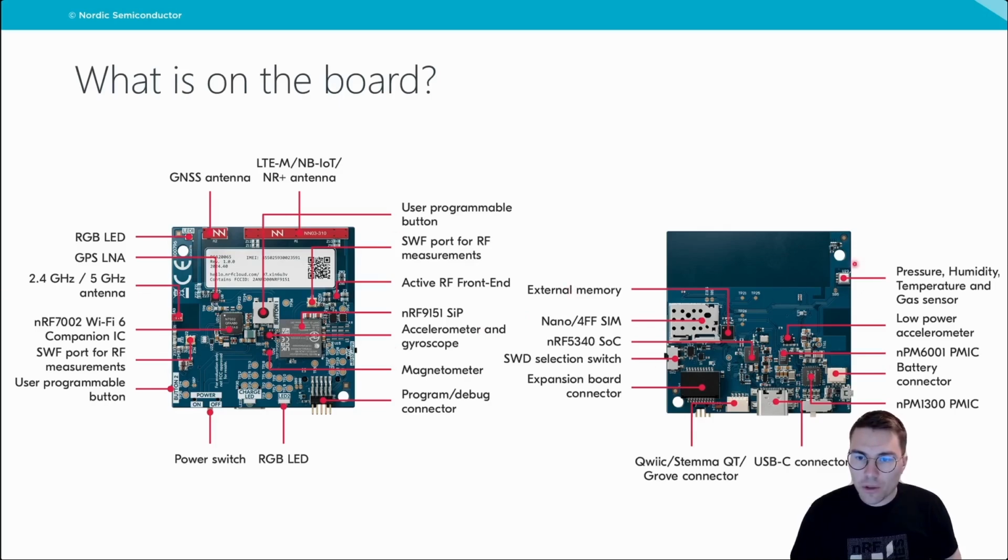On the back side of the PCB, we can see the pressure, humidity, temperature, and gas sensor located here, as well as some PMICs driving different sensors, but also this NPM 1300 PMIC, which is responsible for the battery charging of the device, as well as accurate fuel gauging, so giving you an accurate percentage of the life left of the battery. And in the middle here, you have the 5340 SoC and the expansion board